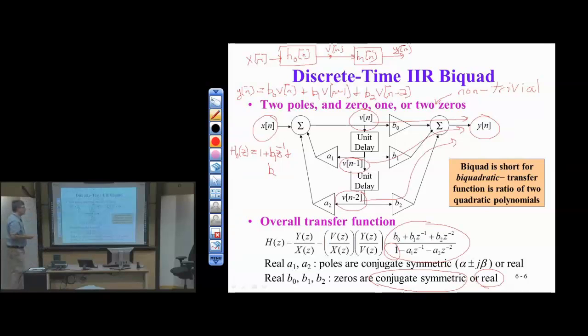Okay, now, if you look at the left half of this biquad, it's nothing but feedback. I have v of n. So now if I look at the input x of n, and v of n now is the output, we're going to look at the left side here. So now v of n flows back to x. And if you look at this, this is exactly the block diagram I had on the previous slide. This left half of the biquad filter structure is the all-pole section. It's the feedback section, and it's just like the filter on the previous slide.